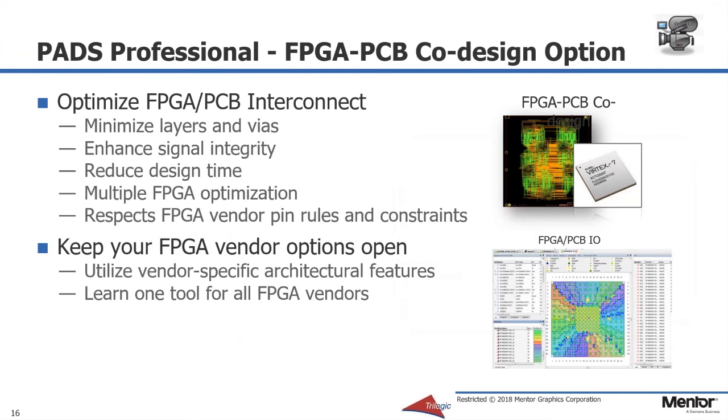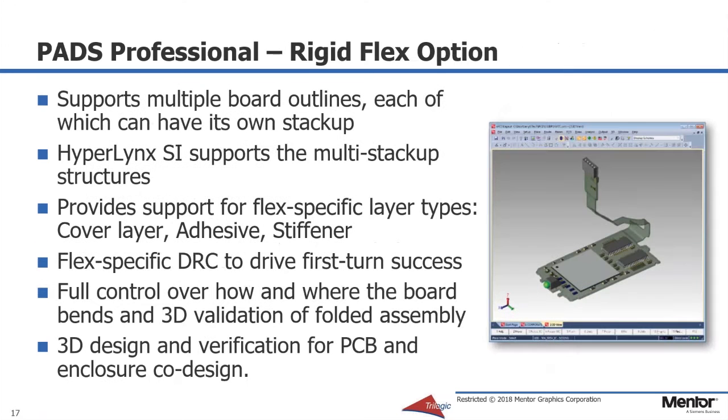One of the advanced options available with the PADS Professional is FPGA PCB co-design. This software automates the optimization of the FPGA and PCB integration. It understands the architectural features of your specific FPGA and facilitates forward and backward changes to the FPGA and the PCB pin designations to improve the routability of the design.